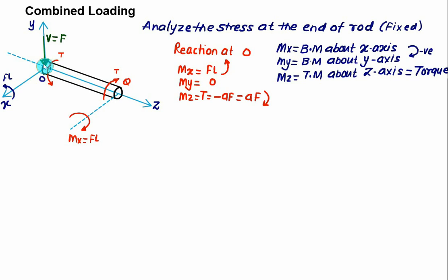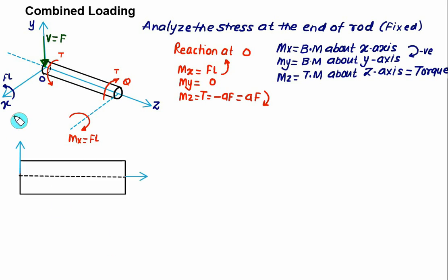So on this cross section here, which is a circular cross section, we have to identify the effect of bending moment, the effect of the shear stress due to torsion, and the shear stress produced. This shear force is due to bending. To observe the effect of bending moment, we'll visualize from this side. In that case, this point is equal to O, this point equal to Q, this axis will be the Z axis, and this axis will be the Y axis.